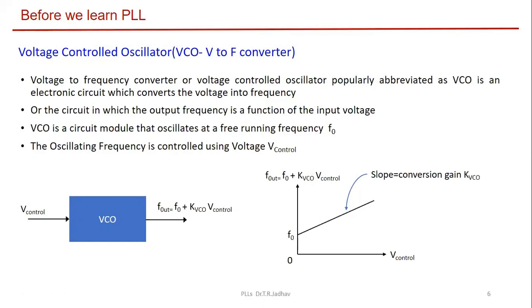It means the voltage controlled oscillator will oscillate with its own natural frequency, which is dependent upon its timing capacitor and resistance. Here in the block diagram, I have not shown the resistance and capacitor, which are the timing components, but through these timing components, later in the design, I will show you that we can set the free running frequency.